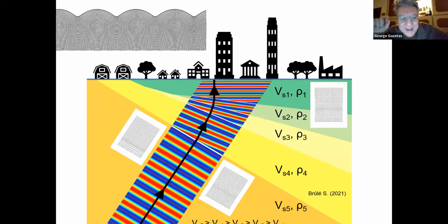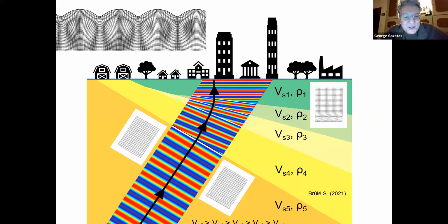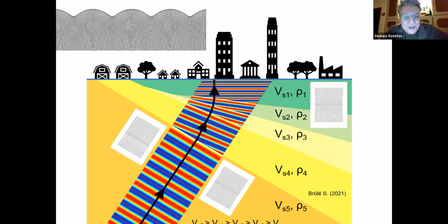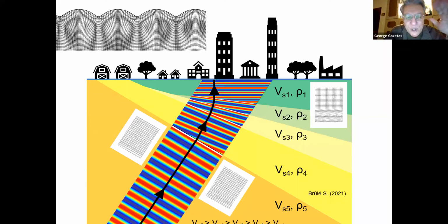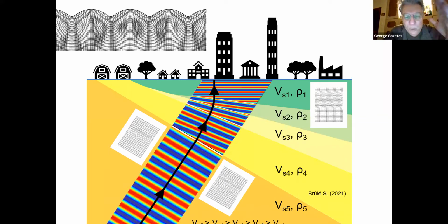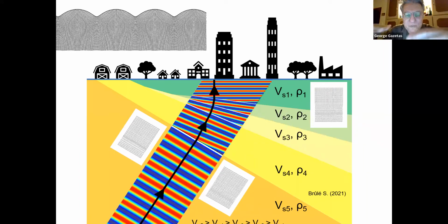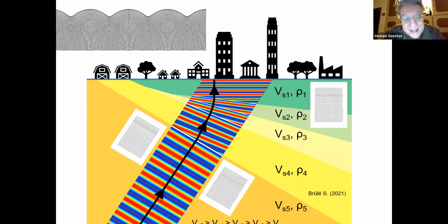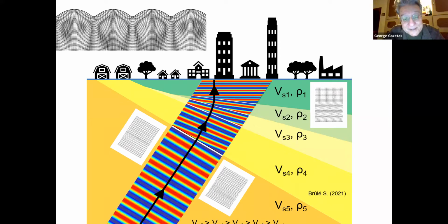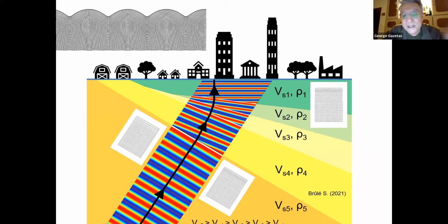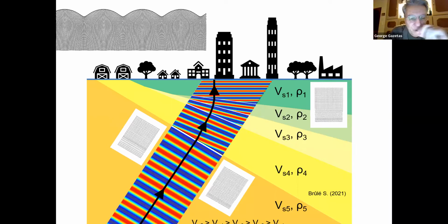May I say something? May I interfere a little bit? Excuse me, Professor Gazetas. Yes, can I say something just on this picture? Even with purely horizontal layers, we will still have the bending of the curve upward. It's Snell's law of refraction, going from stiffer to softer soils. The additional thing that inclined layers will do is create Rayleigh waves, or SH Love waves, depending on the situation, at the very edges, as I think Stéphane mentioned already.